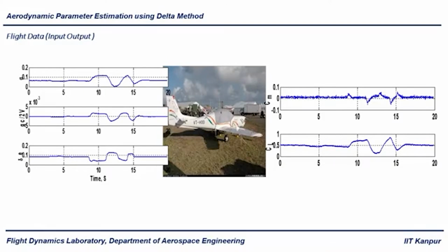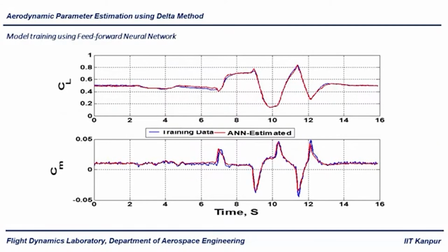And this is the model actually. So this is your aircraft HANSA-3, where you are no more worried about the physics of the HANSA-3 aircraft. Now you are treating this as a black box model. You have gathered the data from flight in terms of sets of input and sets of output data, and you are trying to replicate this model using the philosophy of artificial neural network, which is a very powerful method. As I said, it can approximate any nonlinearity, and once you have this trained model